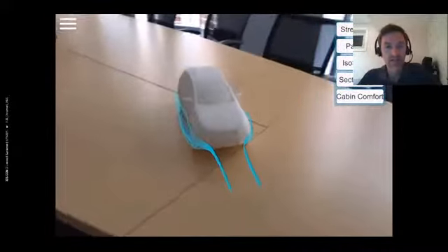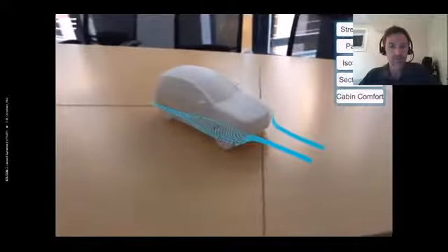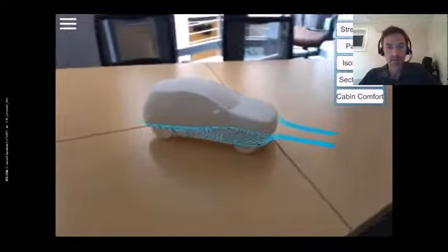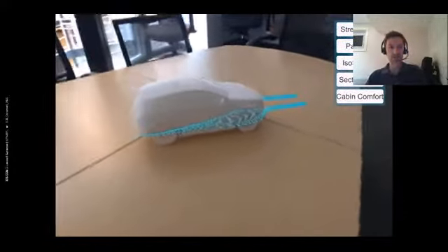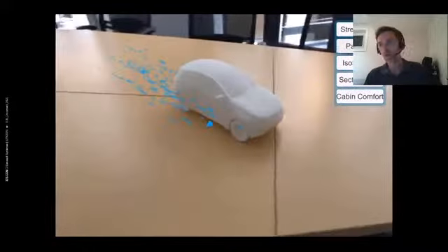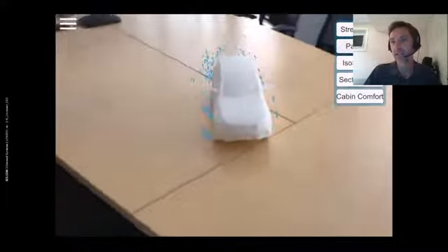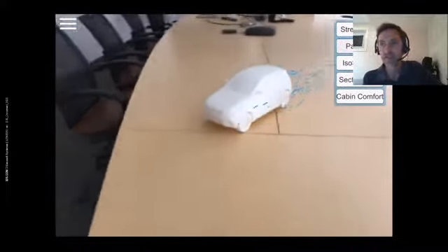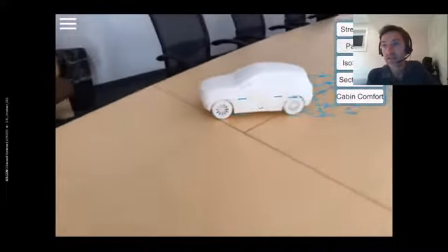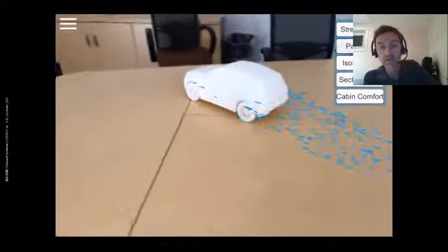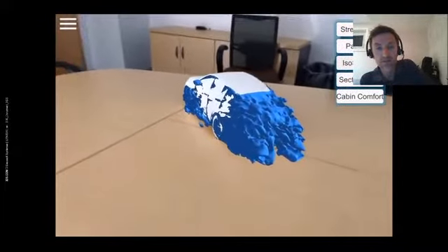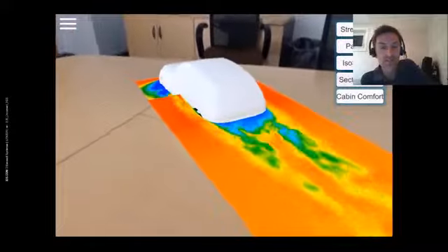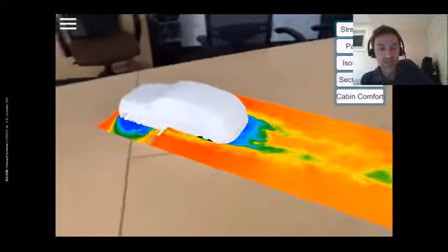This is the first prototype we've made using the VisionLib technology. Using one of our 3D printed models, we brought some existing simulation coming from PowerFLOW technology. The app lets you overlay external streamlines, static and animated, over the car, over the exterior, and over the wheel in different ways. We have static meshes and 2D planar meshes showing the wake behind the vehicle.